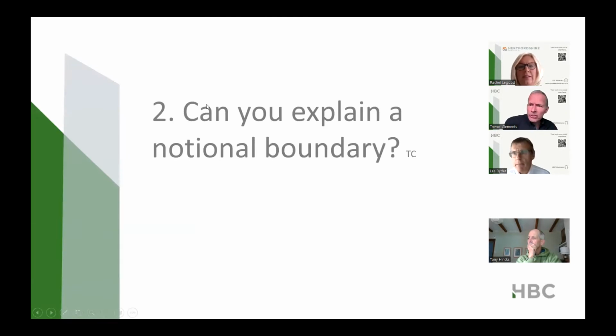I would say, I'll just chip in on the back of Les, and he can do the same on my answers. Les said plasterboard class B, and generally it is, but I know you can get class A2 plasterboards, which is handy because otherwise you wouldn't be able to use them on 18 metre plus high-rise residential buildings. So in case somebody's sitting there thinking, well, how are they doing that? Well, there are plasterboards available. You're 100% right, Trev. It's the paper that's replaced, isn't it? I'm not sure how they do it, but they've got it classified and it can be used. But building control need to be sure that it is the right plasterboard that's had the testing and has got the certification.